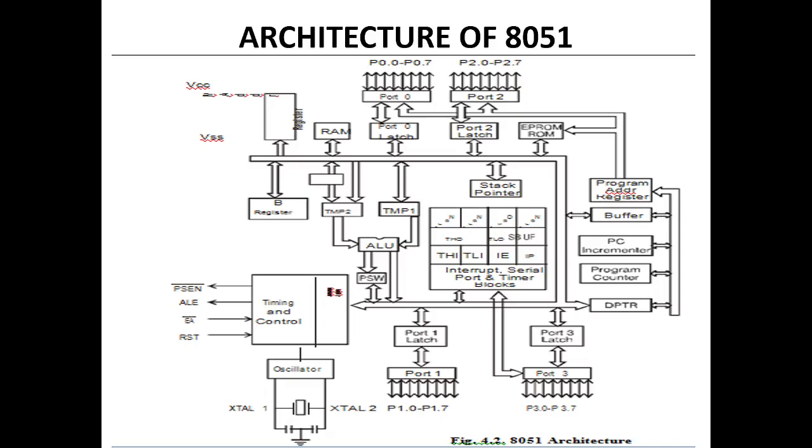And then PSEN, that means program store enable. This is an output pin and the pin number is 29. In a microcontroller based system in which an external ROM holds the program code, this pin is connected to the OE pin of the ROM.